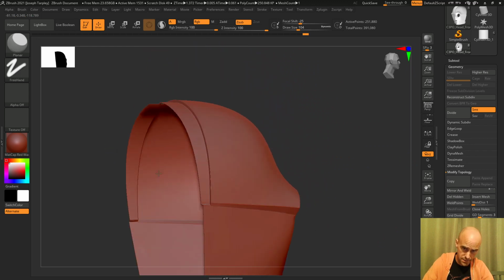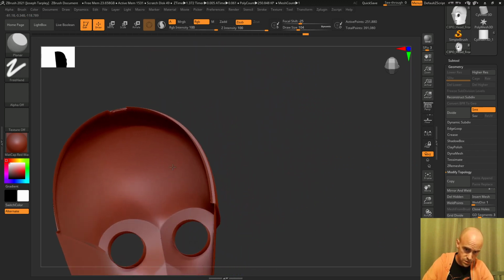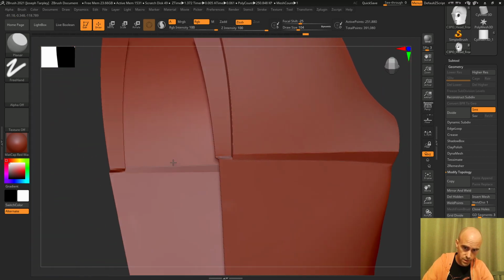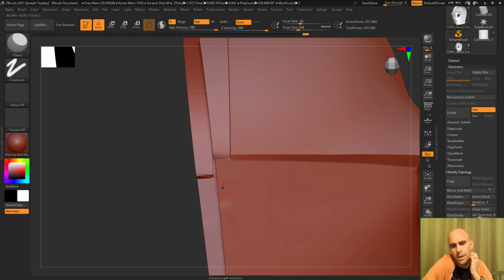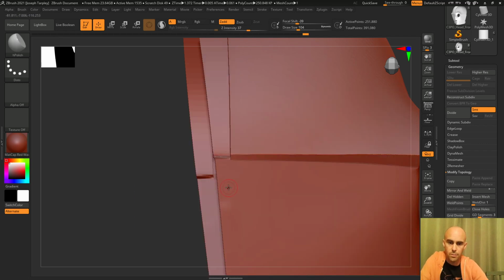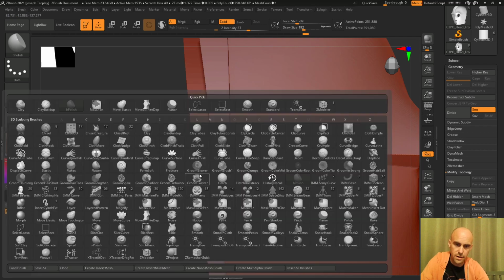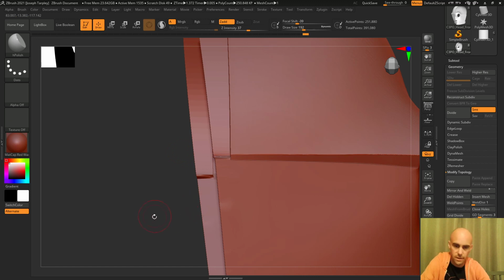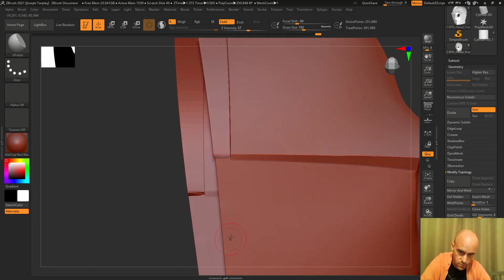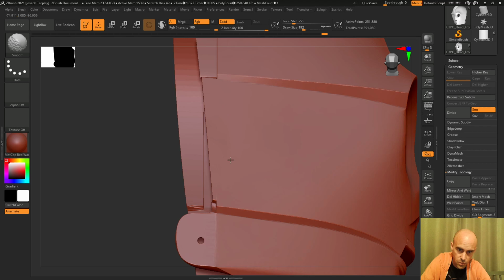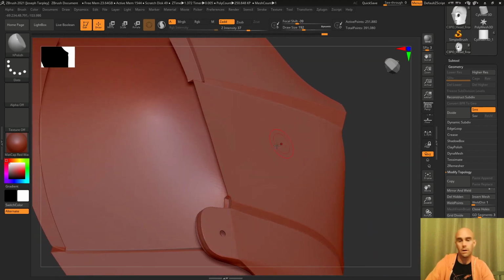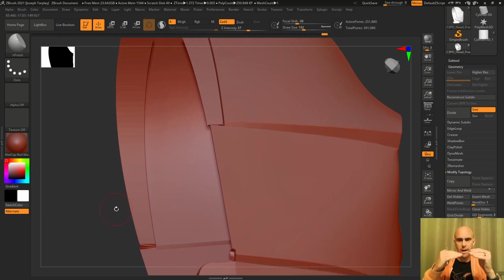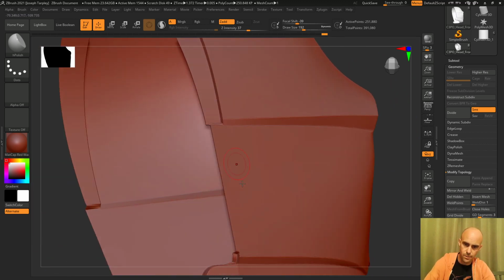I don't have the newest version of ZBrush installed, but should be pretty close. So for this section, I'm in the same boat. I'm actually going to polish this really quick. What I clicked on is B, H for H polish. You can see that selected, and then P, and that gives me that. This is a real subtle way to smooth. You kind of go back and forth over an area, alternating with the Alt key, to push up and down slightly, and it'll smooth that out so you get a pretty nice surface.